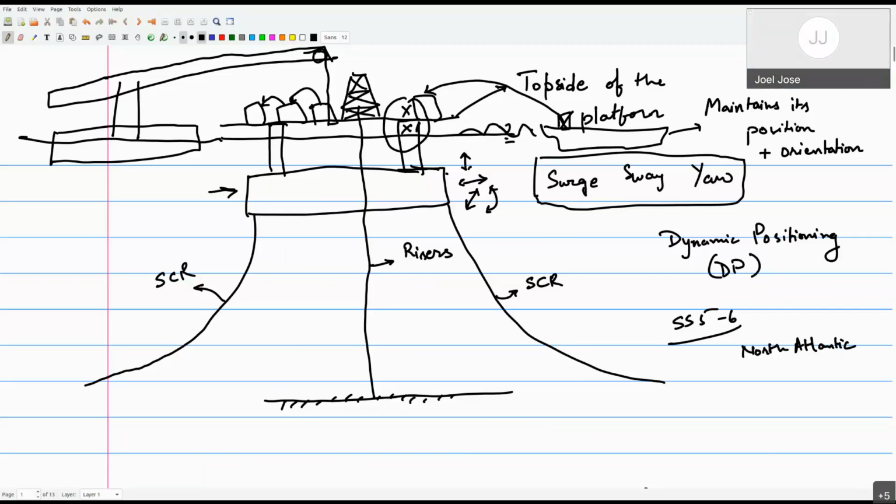Yeah. So for these purposes, it is very important to maintain the horizontal position and orientation of the craft, which is why many times when we are looking at DP operations, we restrict ourselves to the so-called horizontal modes, because the wave loads we can't really avoid. We know that there will be some heave, some pitch, and some roll, but typically in an ocean they will be smaller in number. So you won't see pitch by 10 degrees or 20 degrees. Similarly, roll you will not see by a huge amount if you have designed the vessel well.